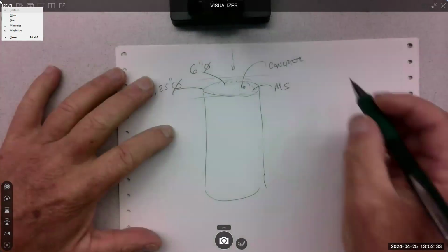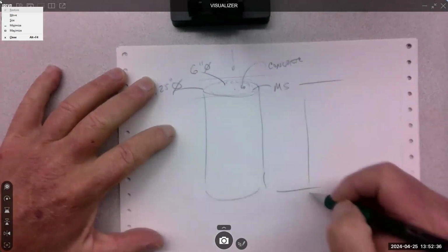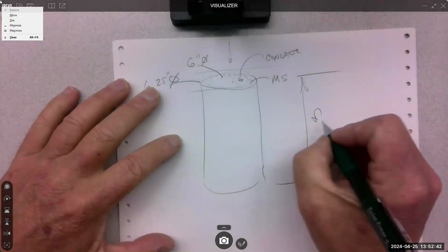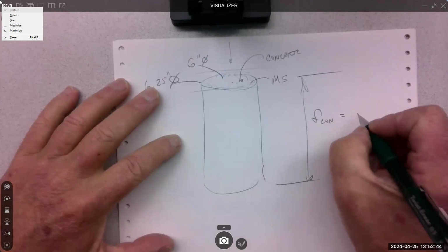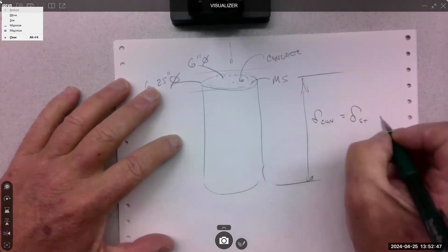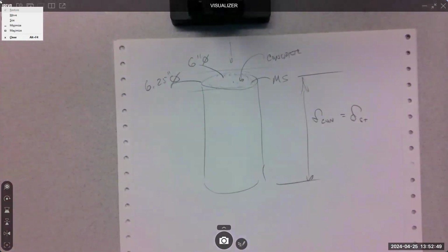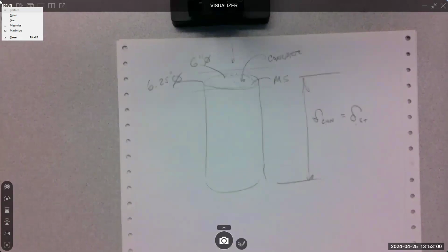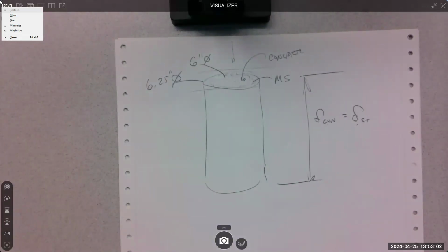And what's important about that is when it changes in length, because when we put these massive loads on it, it's going to deform, right? The change in the concrete is equal to the change in the steel. In other words, the elongation has got to be the same, right? When it squishes the same amount, we can then set those two formulas equal to each other. That's the formula magic of it.